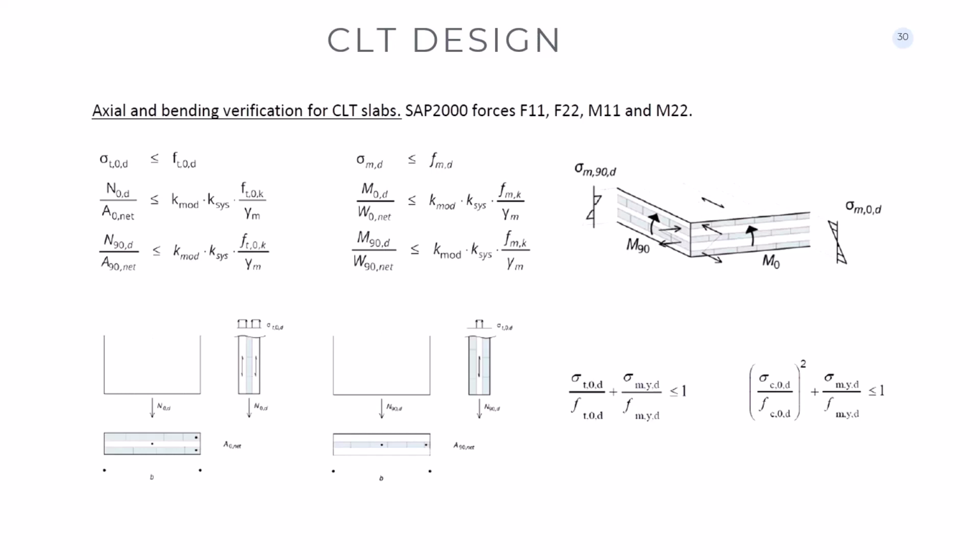And now instead, because essentially this is all covered, they glue together these lamellas that are relatively thin. They are 100 millimeter by 20, more or less. This is the typical ratio. And they attach it in two directions. So this goes in this direction, this one goes in this direction. The typical CLT has always 5 layers. So you get 5 in one direction, 2 in the other. So you get a pretty decent material that spans in 2 ways. Of course, one is the main span that is stronger, one is a little bit weaker.